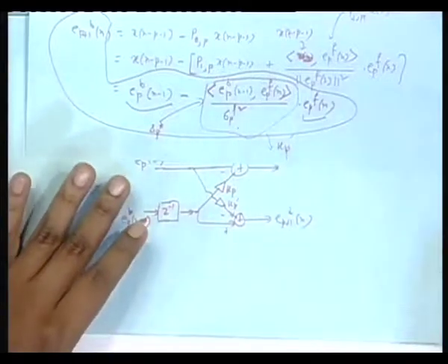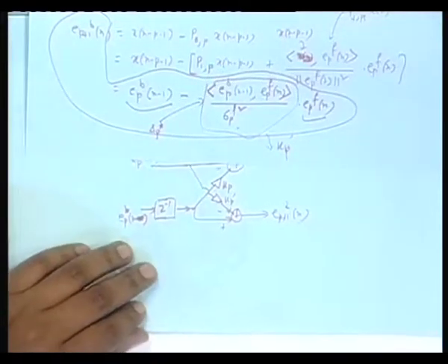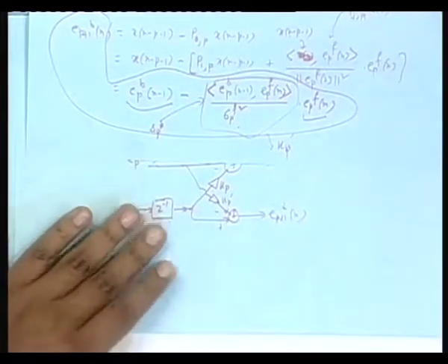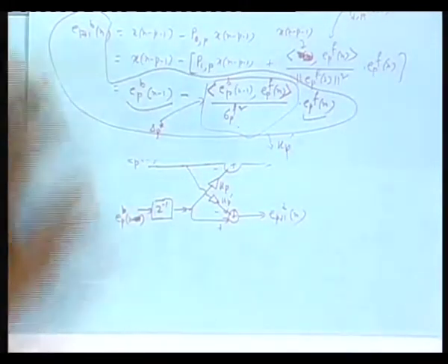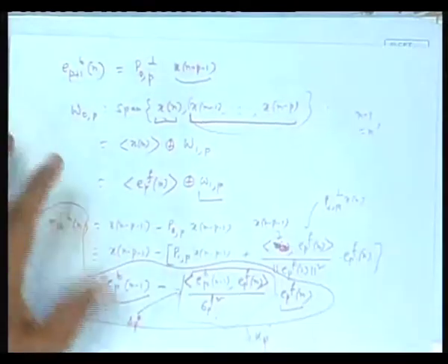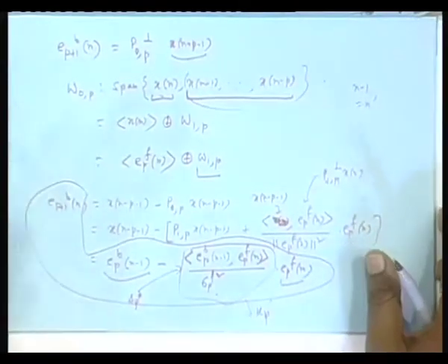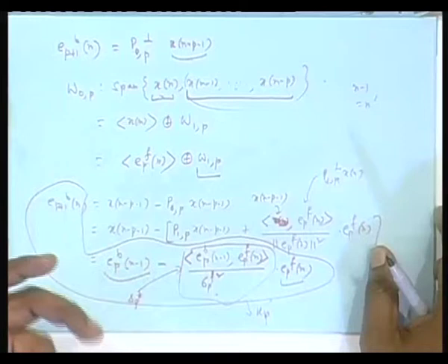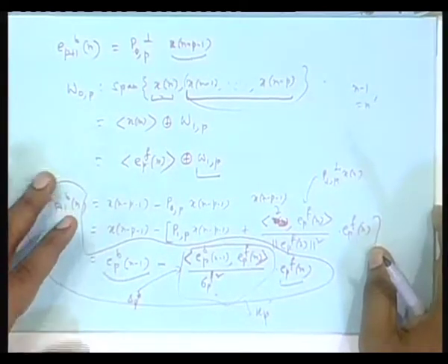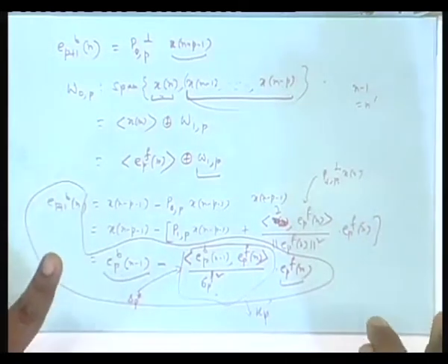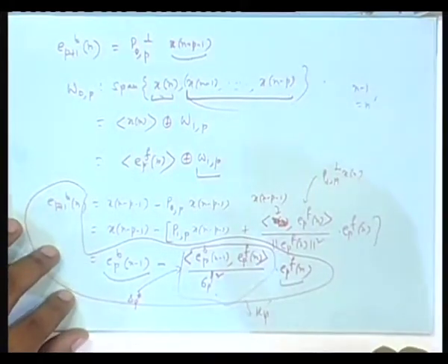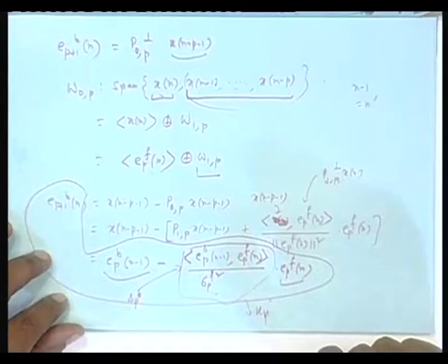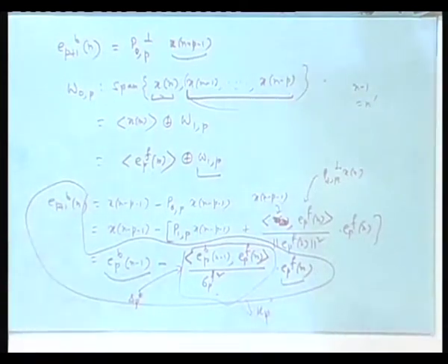Using that, if you want to use this lattice filter, we will develop the entire lattice filter for doing something like autoregressive modeling. You know something about this, right? Did I discuss it in this course? Power spectrum estimation, AR modeling and all that. I will do a fair bit of that also. So, the stability of the filter will be guaranteed because of this fact that the reflection coefficients have magnitude less than 1. We will get not only causal but also stable filters.